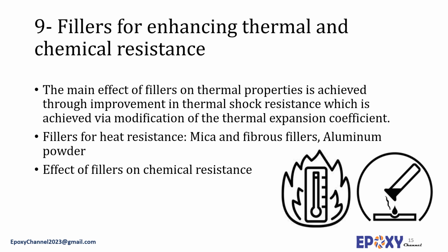Fillers often have a significant effect on the moisture resistance, the moisture vapor transmission rate, and the solvent and chemical resistance of the cured adhesive bond. The effect, however, can be in either direction. Some fillers, such as calcium carbonate, tend to lower acid resistance, whereas others, such as silica or aluminium, may tend to lower alkali resistance. Many fibrous fillers exhibit a wicking action for moisture.